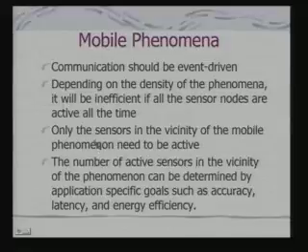Therefore, you can realize that the design of such sensors also becomes an issue, because typically an external event has to trigger that sensor. So, normally what will happen? Such nodes will be sleeping. When the target is in the vicinity, that is, when the sensing element senses the target, what will it do? It will generate an interrupt to activate the system, which can now start processing the data.